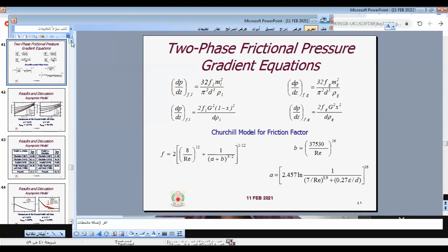One last note regarding friction factor and Reynolds number. My PhD advisor, during his PhD on low Reynolds number heat exchangers at the University of Waterloo, developed a new form for calculating hydraulic diameter in the case of laminar Reynolds number. He showed that instead of using the usual hydraulic diameter for non-circular shapes, which is 4 times cross-sectional area divided by wetted perimeter, we can define the hydraulic diameter as the square root of the cross-sectional area.